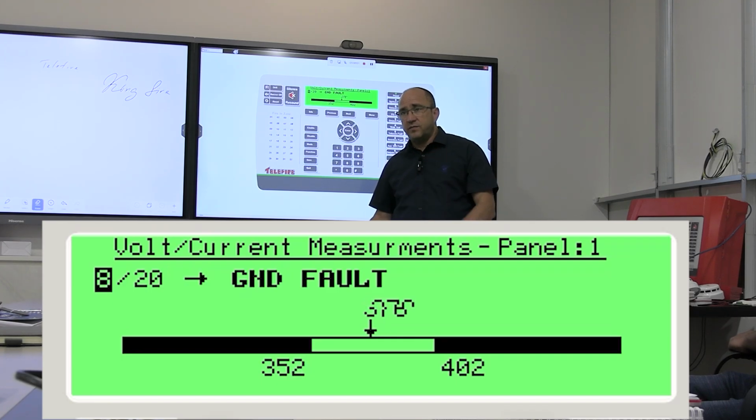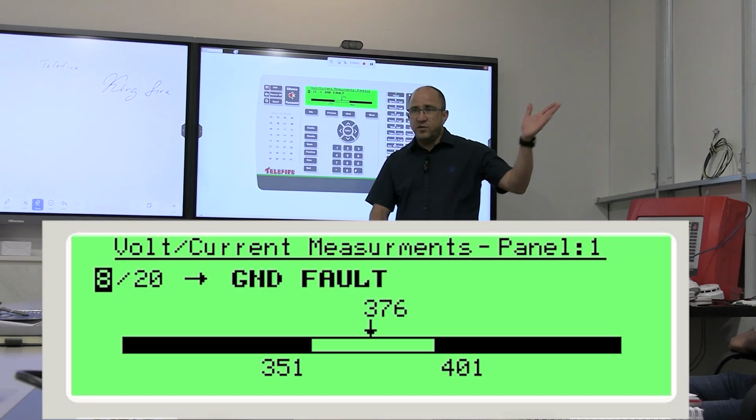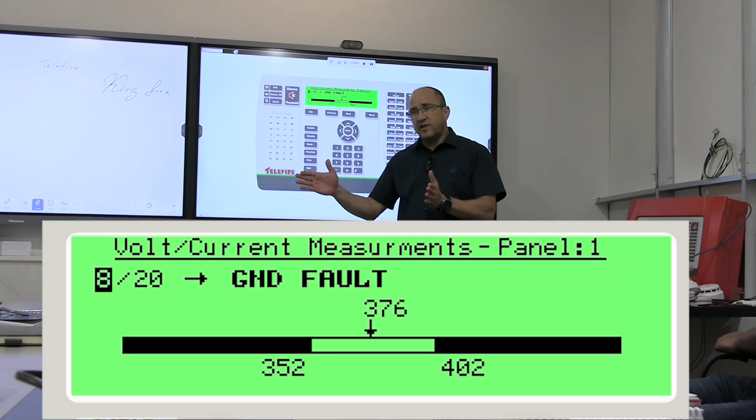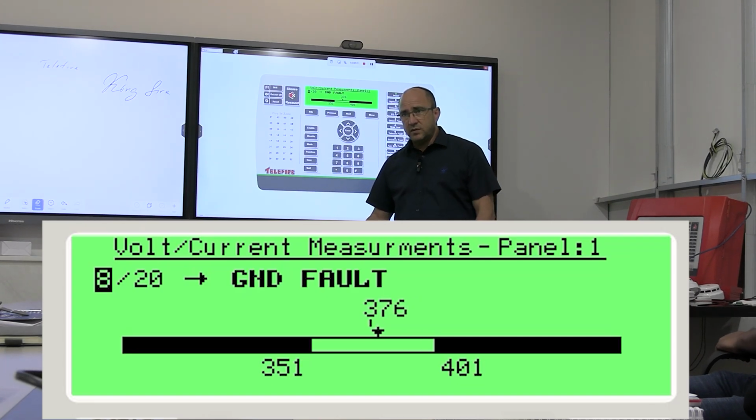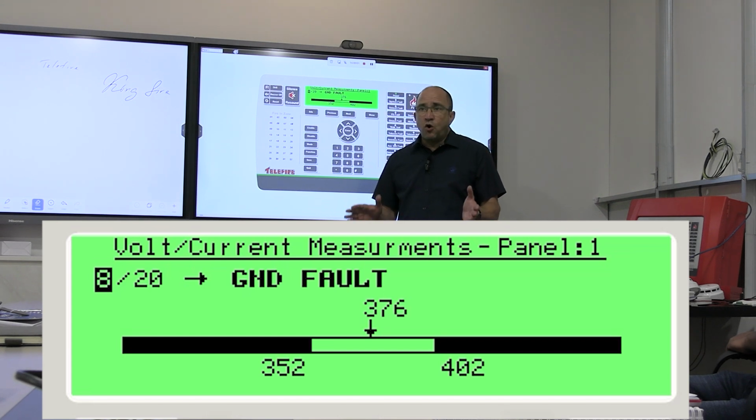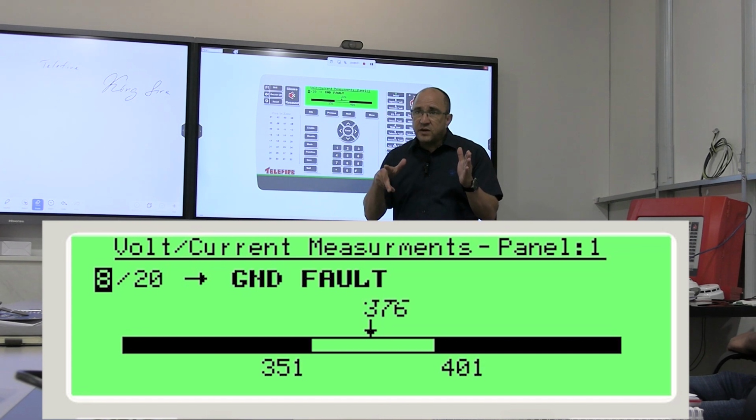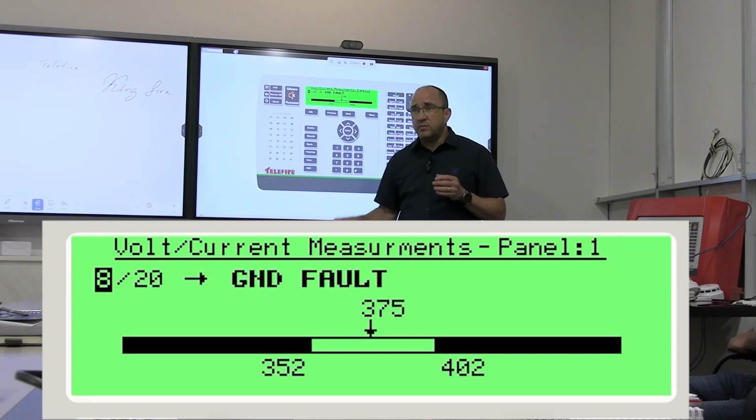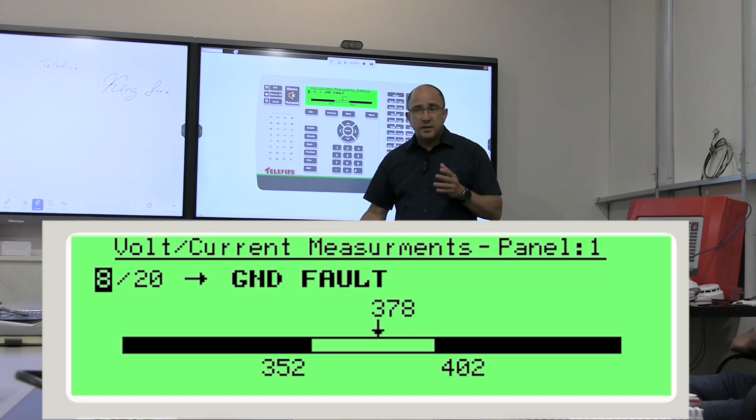You cut it in half. 25 meters, perfect, works. The next 25 meters, you know the problem's here. Now, if you don't mind having 10 meters, 5 meters, 6 meters, the other 25 you can also cut. So you'll have small extension cables. But in the end, you'll find what's going on and bye-bye.